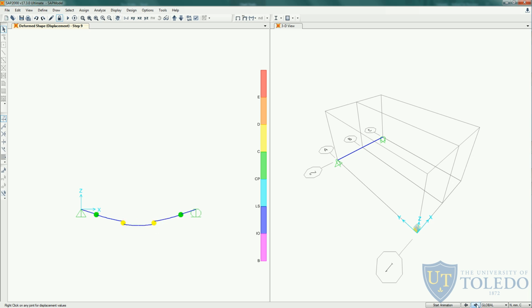So I'm just gonna keep progressing it, and we can see that the shear hinges at the middle start to go into some pretty heavy loading. I'm gonna keep going, and now we can see that the moment hinge at the middle started to displace past the yielding point. So we can see a junction between a shear critical behavior and also a flexure behavior here. So we can expect some plateau in our response due to the yielding of the moment hinge. Let's continue. And right here, the shear hinges in the middle fail, and in our response we see a sharp drop in the force displacement response.